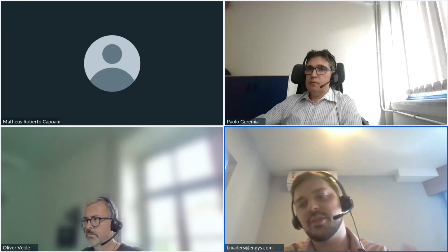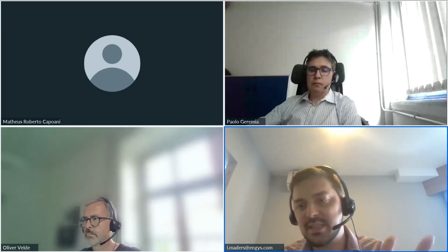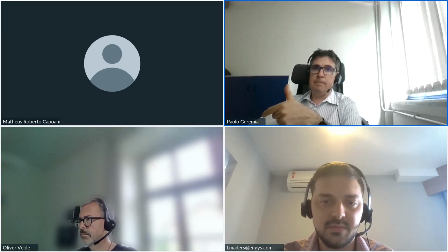Yeah. So if I'm a customer and instead of a steady state MRF approach or transient MRF approach, I want to create scripts or edit those scripts to match my existing workflow, that's totally possible because that's included in the Helix macro Python API, right? So I could literally customize this integration. Is that correct? That's correct, exactly. In the case we showed today, we basically use the steady state MRF approach, but you can easily customize it and use the transient approach instead, with the dynamic mesh motion, of course.